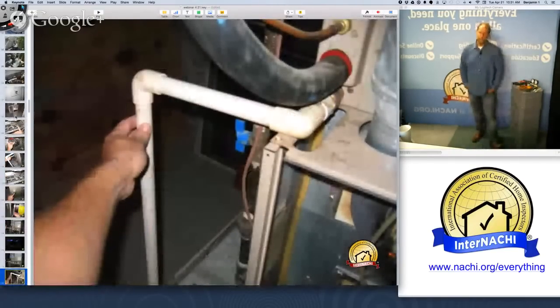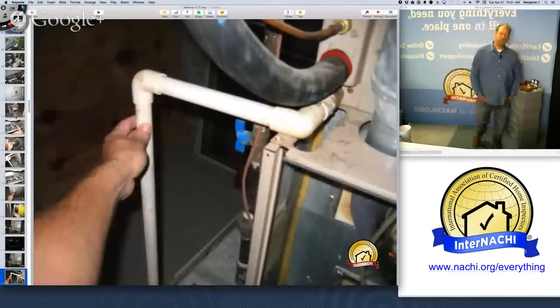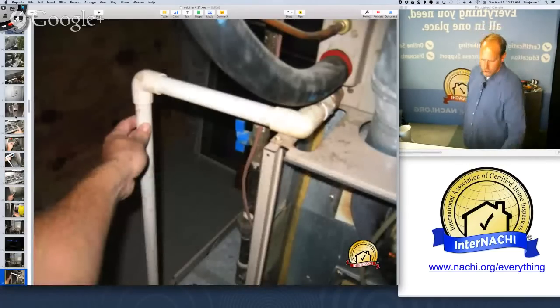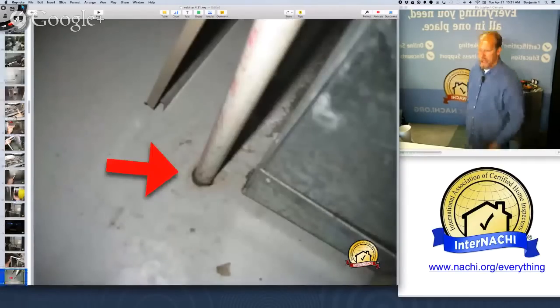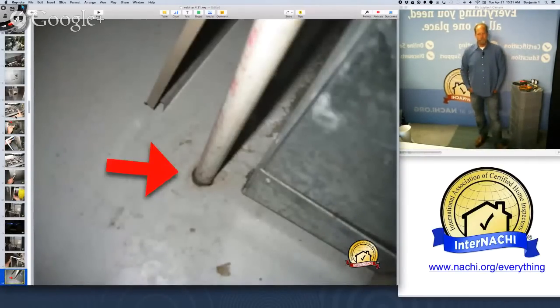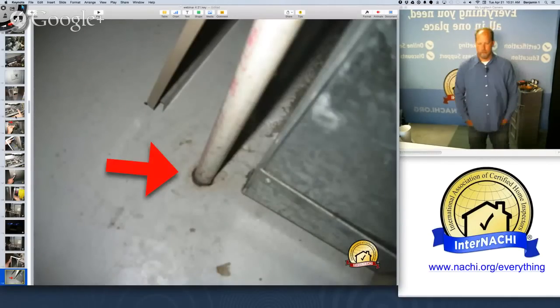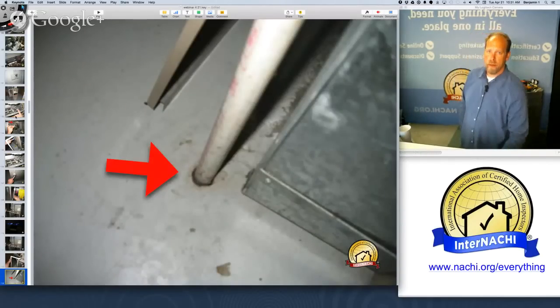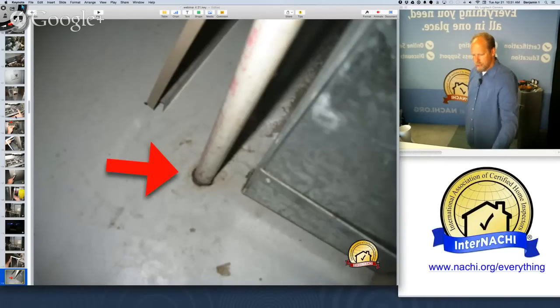You don't want to be sucking things into the ductwork through an open condensate drain pipe. And the drain pipe, this is a common thing with some builders. They stick the drain pipe in a hole and they drain it under the basement floor. Ideally, it would go into a pump and properly controlled and discharged, either outside or into a sewer system. Typically, it goes outside.